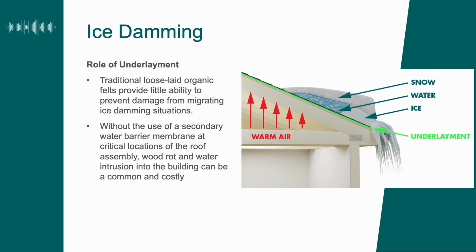Now, if you're using traditional underlayments, they do serve as a barrier to the sheathing. But when ice damming starts to occur, they're not typically sealed. They're not typically sealed to the metal. Everything is just overlapping.